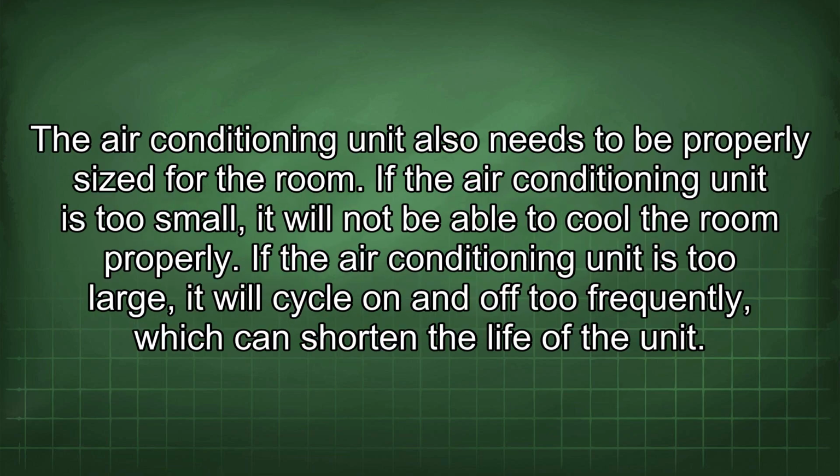The air conditioning unit also needs to be properly sized for the room. If the air conditioning unit is too small, it will not be able to cool the room properly. If the air conditioning unit is too large, it will cycle on and off too frequently, which can shorten the